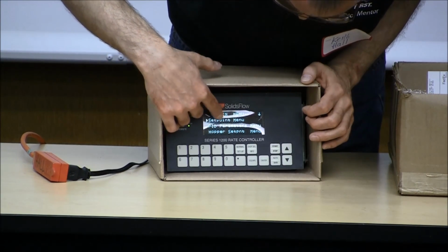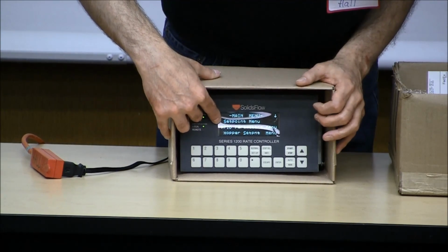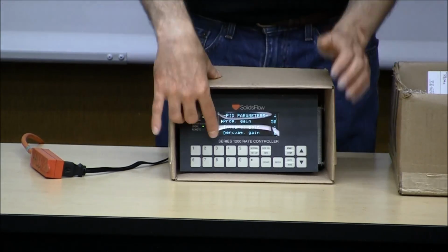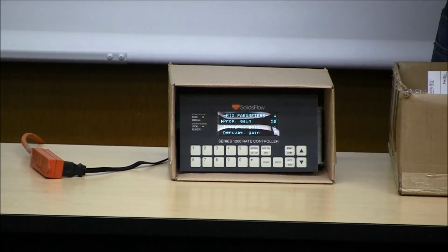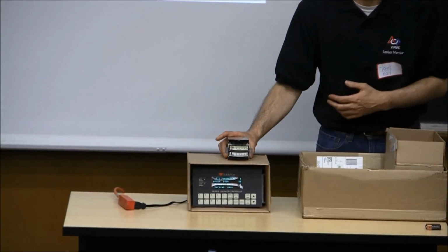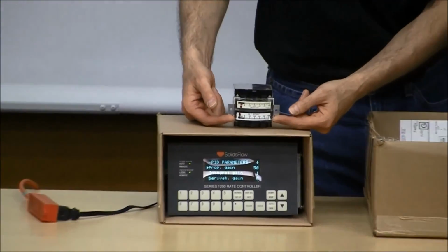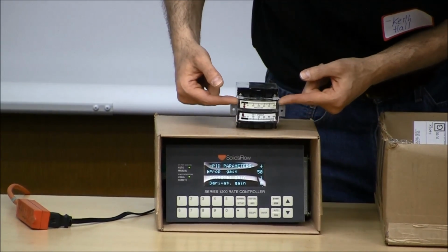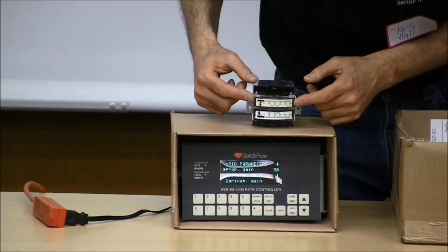Set point menu, then the parameter menu. Can you see this? If I go into my parameter menu, there's my proportional, my integral, and my derivative. So I'm not making this stuff up. The other thing is, from an ancient system, there's a gauge that measures, the bottom one is a measurement of your set point, so that when you walk by on the factory floor you can make sure the set point is set correctly. And then there's something here that just says process, which could be whatever sensor that is.